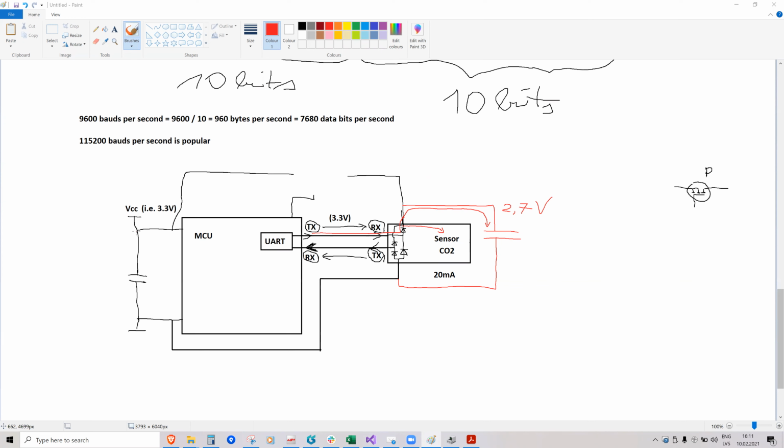The microcontroller told the device to turn off, but after 2 weeks the guy tried to turn on the device and it didn't turn on because the battery was empty, and he couldn't find where the leakage was. It turned out that through the UART pins he was supplying the sensor all the time, and so the battery discharged.